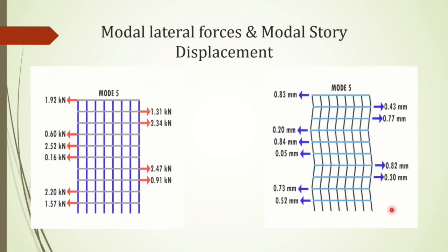Now, if anyone is wondering, where is the positive force here? The positive force here is the one going to the right, and the negative force is the one going to the left. But guys, just take note, we have no negative force. We just call them negative because we set one force as compression and the other as tension. If we set the tension as a positive sign, then the compression is negative. If we set the tension as positive at the start of our solution, then the compression is negative. That's all. There is no negative force.